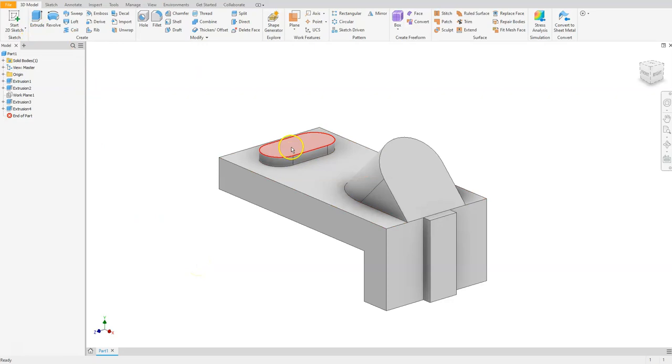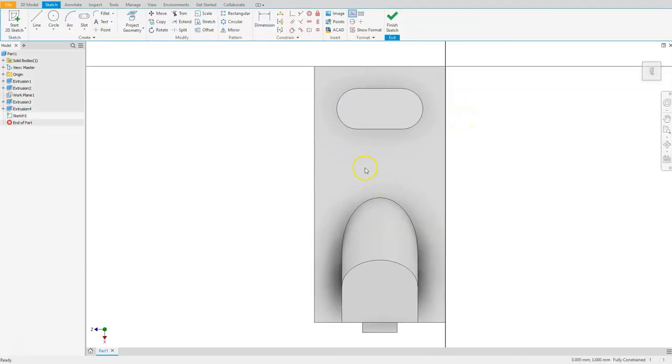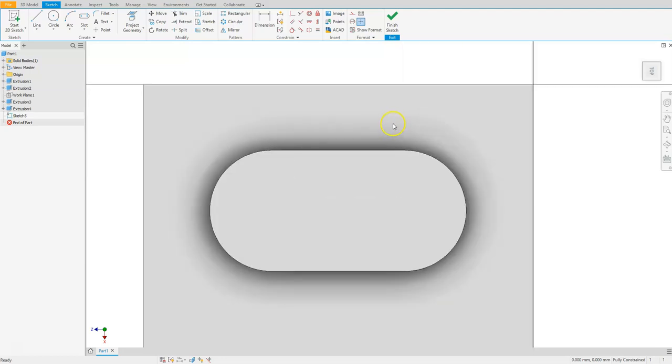Let's go ahead and create our cutout way that's through the top of that slot. So go ahead and select your slot just on the top face of it and choose Create Sketch. Next thing I want to do is bring in the geometry of this shape that I used beforehand. So I'll choose Project Geometry, and I'll select that face of this one and then hit Escape. You can see that you got the two center dots that are located on it.